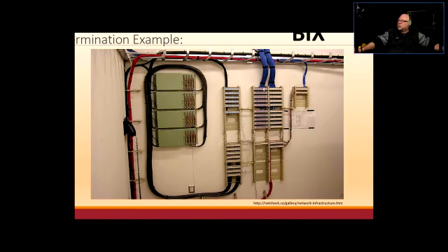So mostly the BIX would be used for POTS lines and some control wiring. However, there are available on the market, not as popular, but still available, Cat5e type of BIX connectors. The ones that we are using are Cat3 rated. These are for POTS lines. You can get BIX termination blocks in a Cat5e version. Whatever you need to use, depending on the purpose of the whole system, you buy the appropriate equipment. But 110 mostly is going to be used in data termination, Ethernet.